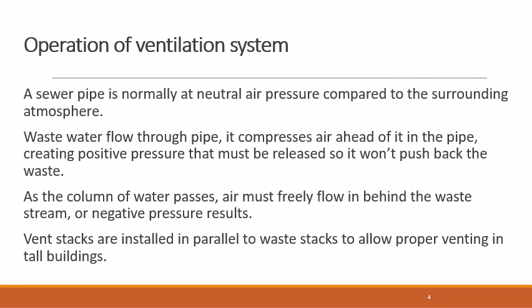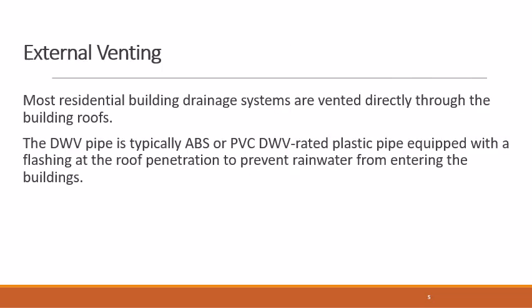So the vent stacks are installed in parallel to the waste stacks in order to allow proper ventilation in tall buildings. In venting, the first one is external venting. Most residential building drainage systems are vented directly through the building roofs, that is, outside the building.